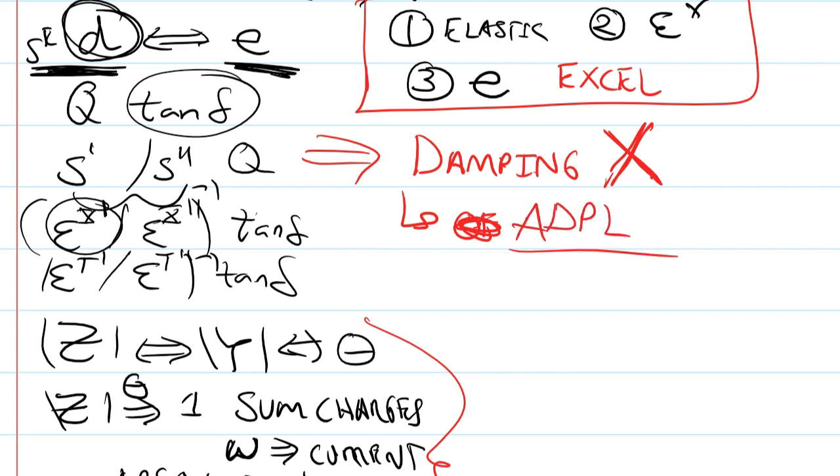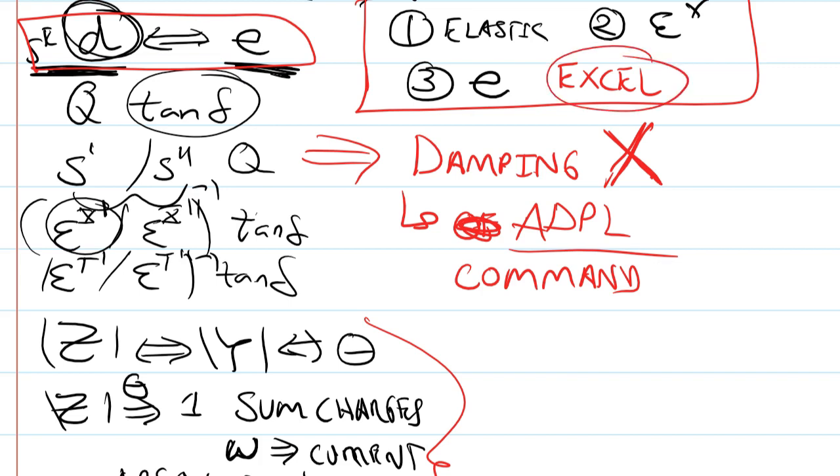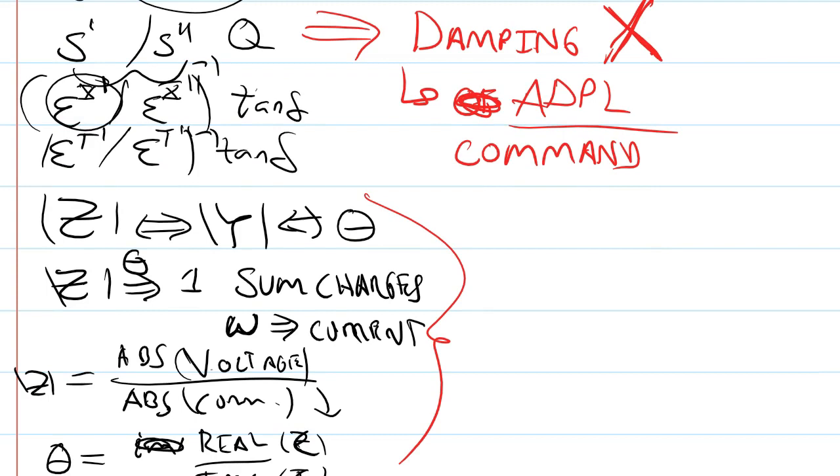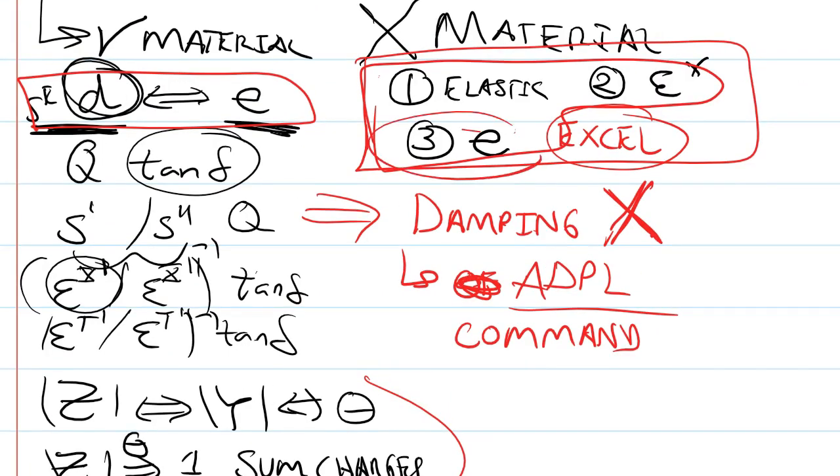I don't know what that stands for. But basically you have to put in a command, which I don't like, where you have to go around the standard way of doing it. It's not hard to put in the loss factor or the command for that, but it's not something I think we should be doing. We should have a choice of which kind of material property input we want. We should also not have to use an Excel worksheet with matrix inversions, and then even on top of these matrix inversions, the method for inputting material properties is still not a standard method. It is the Ansys matrix. So that's not right. You shouldn't make your program so specific that it becomes an Ansys method of putting it in. Not even a standard strain form of the equations. All right.